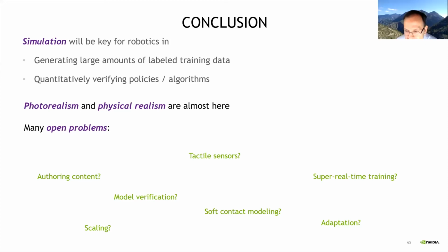Dagoberto is asking, do you train the model from zero to avoid obstacles while accomplishing the mission, or do you use some transfer learning approach? Do you train your obstacle avoidance models from scratch, or do you use transfer learning? For avoiding obstacles, those are all trained from scratch. The videos I showed where we're reaching a point in space while avoiding obstacles were trained from scratch, using, as I mentioned, a curriculum learning approach. We start with an easy situation with no obstacles, and then we slowly add obstacles to make it increasingly more challenging for the network.